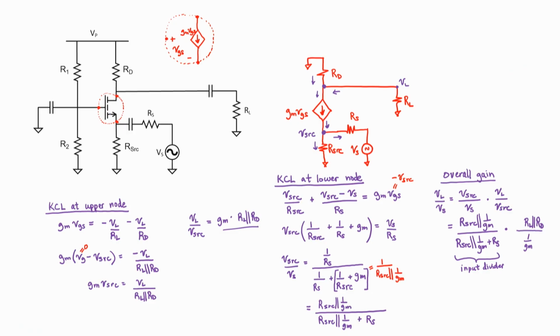So let's go ahead and just imagine that there's a little resistance right here in the transistor. I don't want to call it little Re like I did with the bipolar transistors. Let's instead just label that resistance as 1 over Gm. I like to do that because it creates a close analogy between the bipolar transistors and the MOSFETs. On the right-hand side, I can also separate these two resistors in parallel. This right expression can be split into two expressions. You see, here are the two resistors in parallel.